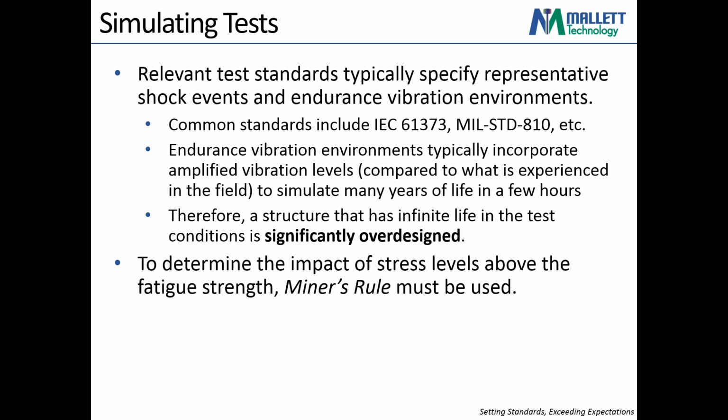So to require yourself to have infinite life for a test case generally means that the structure is significantly over-designed, right? Generally that means that I'm saying this can essentially survive forever, whereas oftentimes we want to optimize our design and make sure it passes tests so it survives a 20-year lifespan that is needed. But we don't necessarily want to make sure it survives 100 years, because that may be unreasonable. There may be other factors that make that non-feasible.